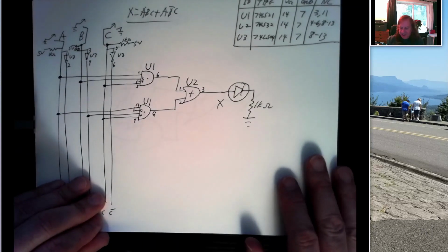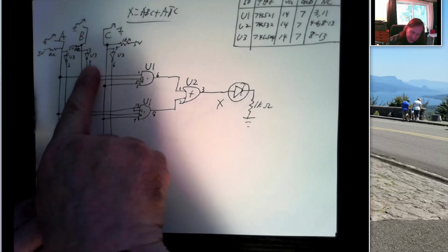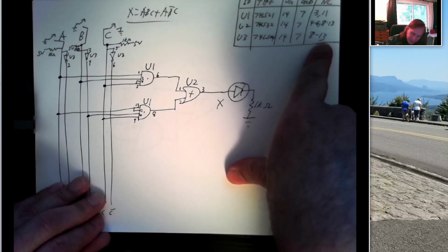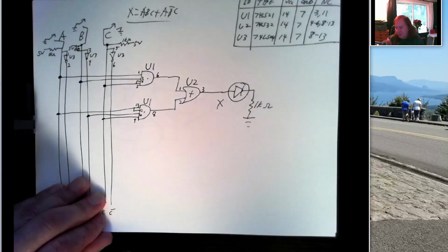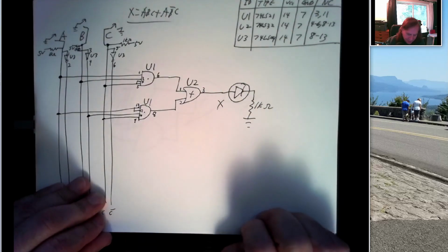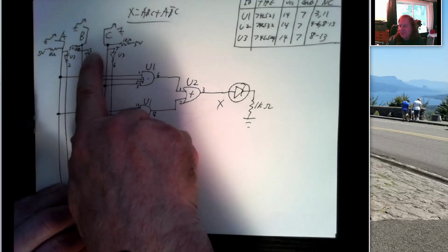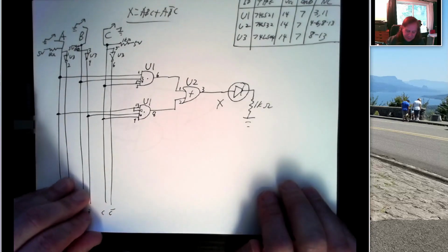And we can spot check our circuit, right? When we're studying U3 and trying to figure out what's wrong, we can eyeball it and say, make sure there's no wires between 8 and 13. Well, if we see a wire going into pin 10, we know something's wrong. And we go and we check our wiring and it's like, oh, this was supposed to go in pin 3. It actually got put in pin 10. Well, you just found your problem.